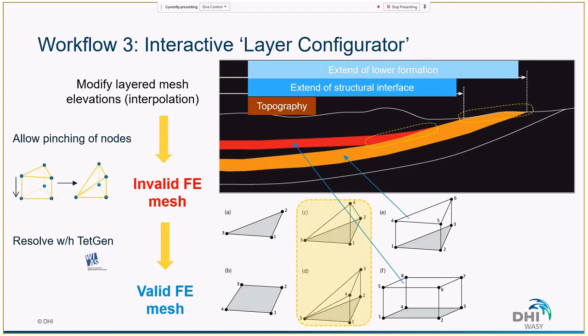You can do a local refinement. So in these areas, on this location where there is intersection, we can use another type of elements, tetrahedrals here. Or you can just remesh the entire layer with tetrahedrals. Or if you want, you can refine the entire model in 3D, in locations with and without intersection, with tetrahedrals.